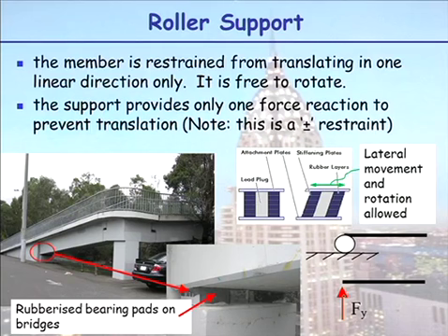So please be clear that a roller support, it's drawn like that. People think, oh, it can flip up. A roller support restrains in the positive and negative direction, okay? No upwards in this case, sideways allowed, rotation. You can have roller supports, horizontal rollers here, or you can actually have vertical rollers as well. And that would be me holding my ruler like that. Or in actual fact, if I have a ladder, which we'll have later, leaning against a wall. So it can move up and down, okay, but it can't move sideways.